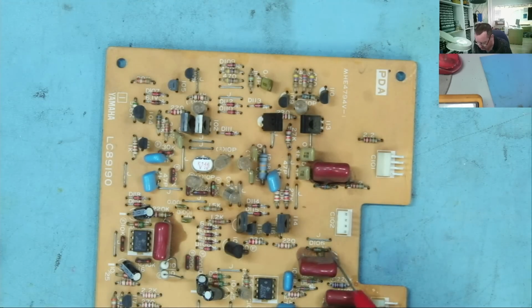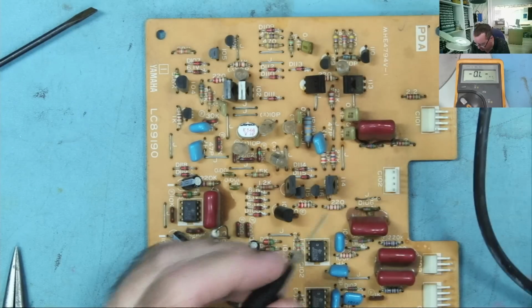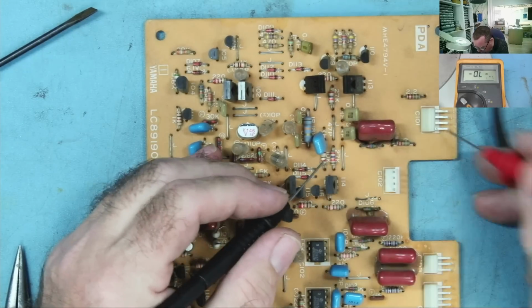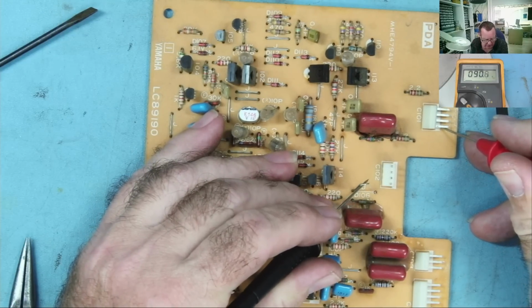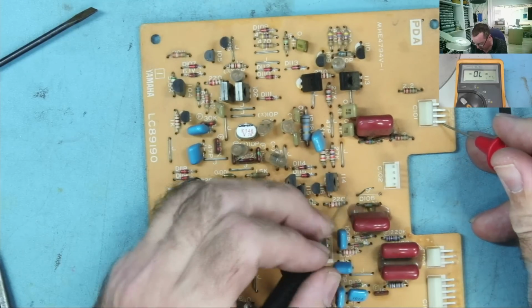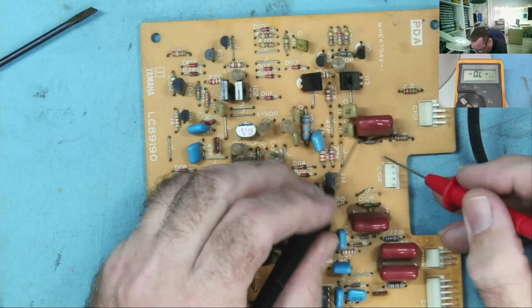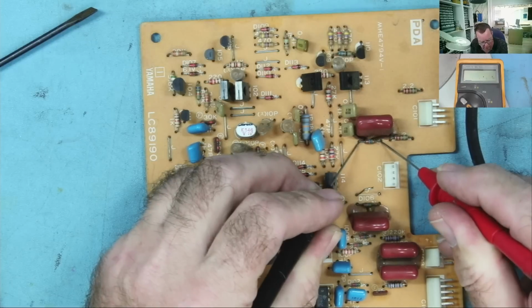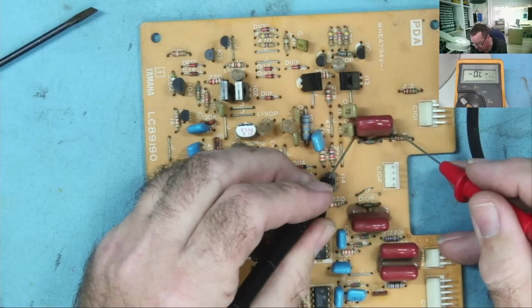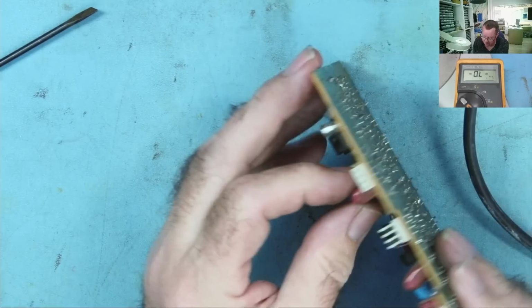Let's lift this one. The wire's lifted out of the board now. So if we go from the input to here, we have about 90 ohms, okay, and obviously there's no connection to there anymore, so the problem does appear to be here. We can see it across the diode. I'll take the capacitor out. Okay, let's just take this out.